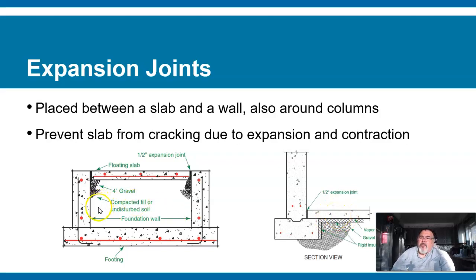This is just showing you in another elevation or detail this floating slab. See, it also has an expansion joint. It's a floating slab between two T-walls, and it's literally resting on top of gravel, on top of dirt. Here, this slab rests on top of the footing. So the concrete footing is holding that slab up over the dirt. Here, the dirt is holding the slab up.